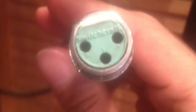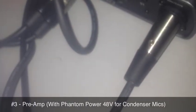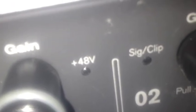This signal is then passed through typically an XLR cable, which can also power the microphone in the case of many studio condenser mics. And though it's another topic, choosing the right cables is imperative in continuing the signal flow and having successful sound recording. Now the third step here would be a preamp, where the signal is received from the microphone. The preamp's job is to basically boost the low-level signal that the microphone typically produces. It then reroutes the signal through an XLR cable to an audio interface.